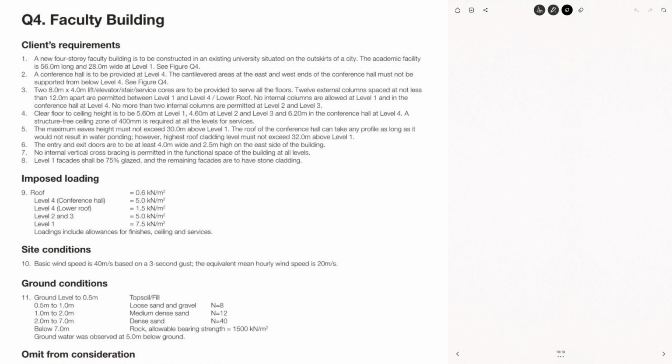And to calculate the reduction factor because of buckling, then I need a lambda. The reduction factor will be dependent on my lambda 1. Lambda 1 would be equal to 19.3 times the epsilon.